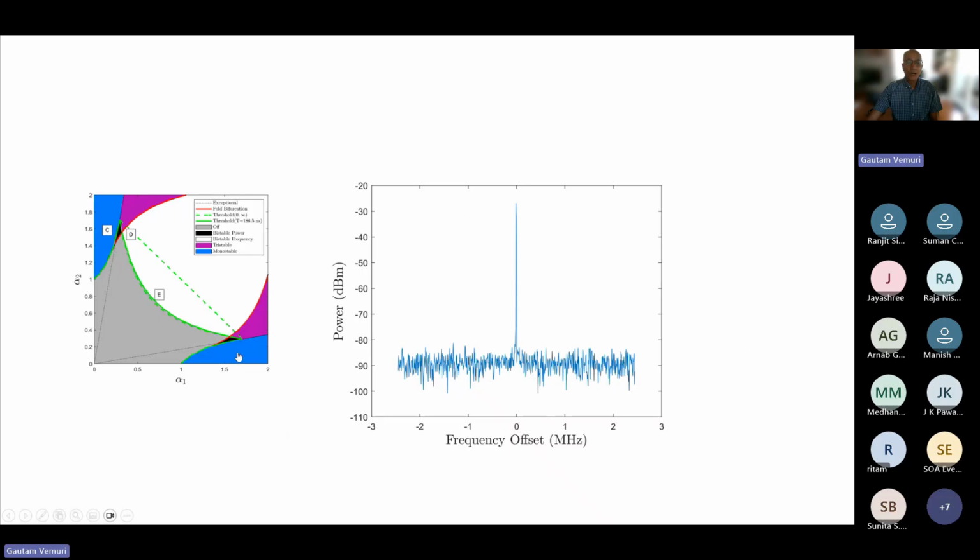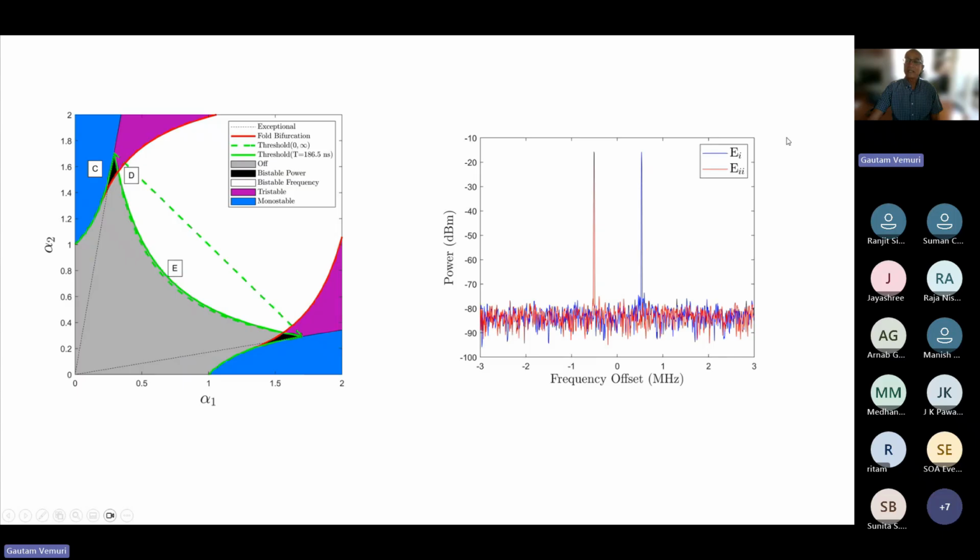This is how things look in this blue region. In this blue region, it's like there's a single oscillator. There should be a single frequency. And sure enough, this frequency offset, I mean, what is the offset from the bandpass amplifier? So the oscillator oscillates at a single frequency that is equal to the frequency of the amplifier. In the bistable, so you see I've labeled them E, in this white region, I said you get two frequencies, and sure enough, you get two which are equally offset from the filter frequency.